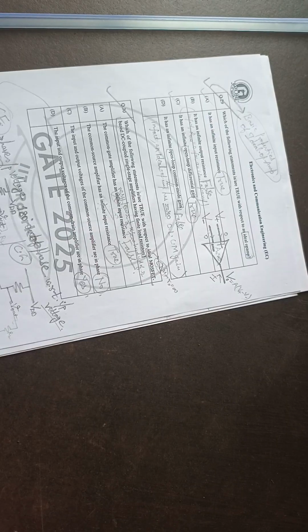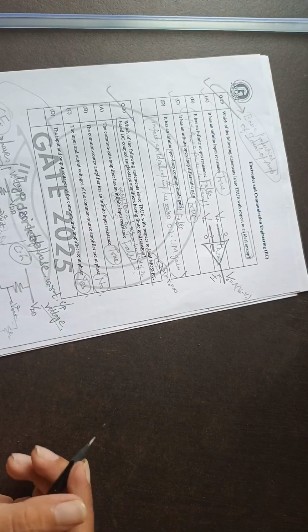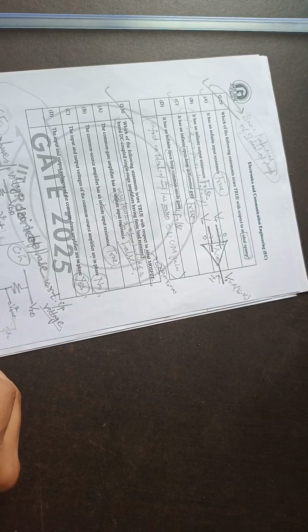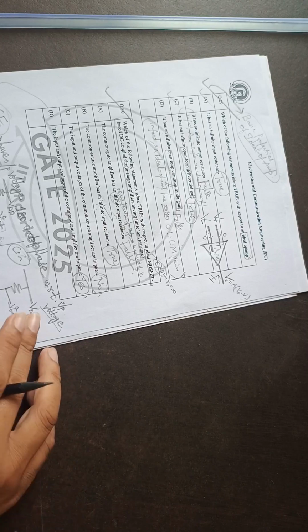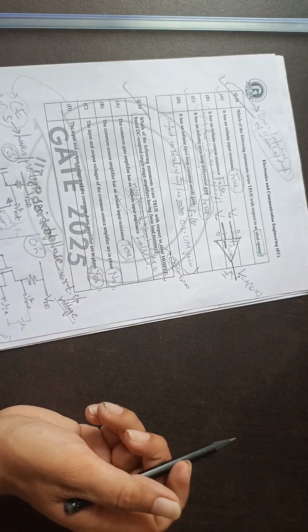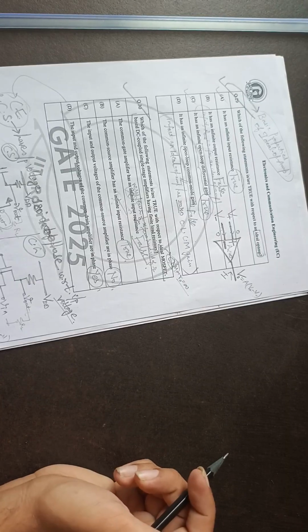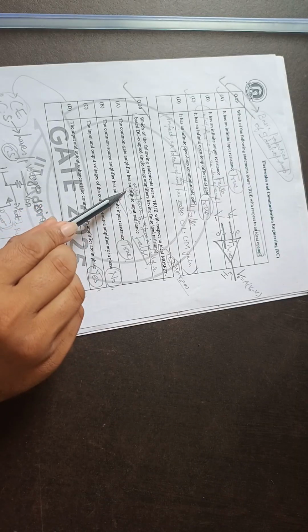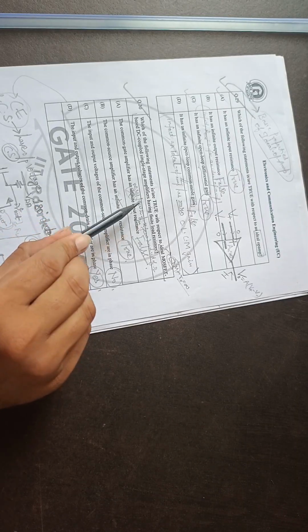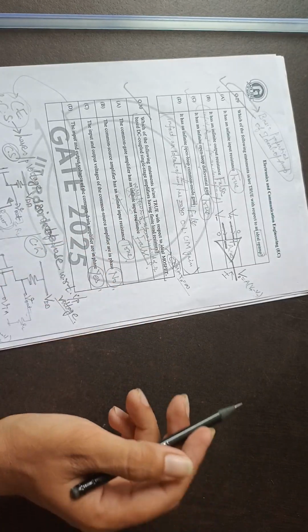Okay, and when we look into the source, then you know that the R_in we usually see is 1 upon g_m. Here it is an ideal MOSFET, so channel length modulation will be ignored, so R_out is infinite, so in that case it will be 1 upon g_m. Otherwise it will be 1 upon g_m parallel to R_out. So common gate amplifier has in fact 1 upon g_m, a very low value, around a few hundreds of ohms, so it has a very low input resistance, so it is a false statement.